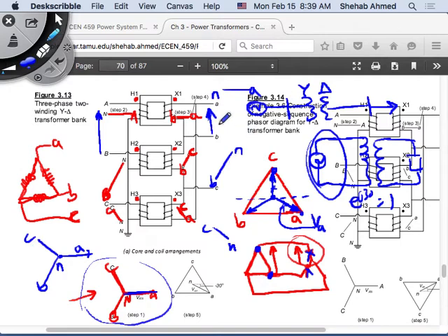But because of the way I connected the transformer in a delta configuration, the labels on the windings are now different. So I measure the voltage between the lines. It will not be in phase. I have to now take this line to line voltage that's not in phase and figure out the corresponding single phase equivalent circuit. What will it look like?